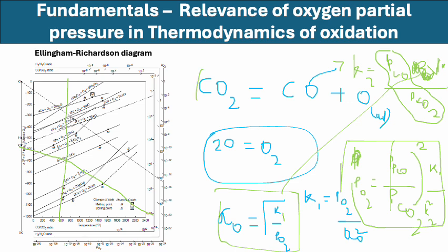So a lot of carbon dioxide molecules must dissociate to carbon monoxide and oxygen for silicon to oxidize at 600 degrees Celsius under this condition. If you keep a silicon wafer at 600 degrees Celsius, and you just purge carbon dioxide into the environment, and the dissociation of carbon dioxide into carbon monoxide and atomic oxygen does not take place, then we will not have oxidation of silicon.